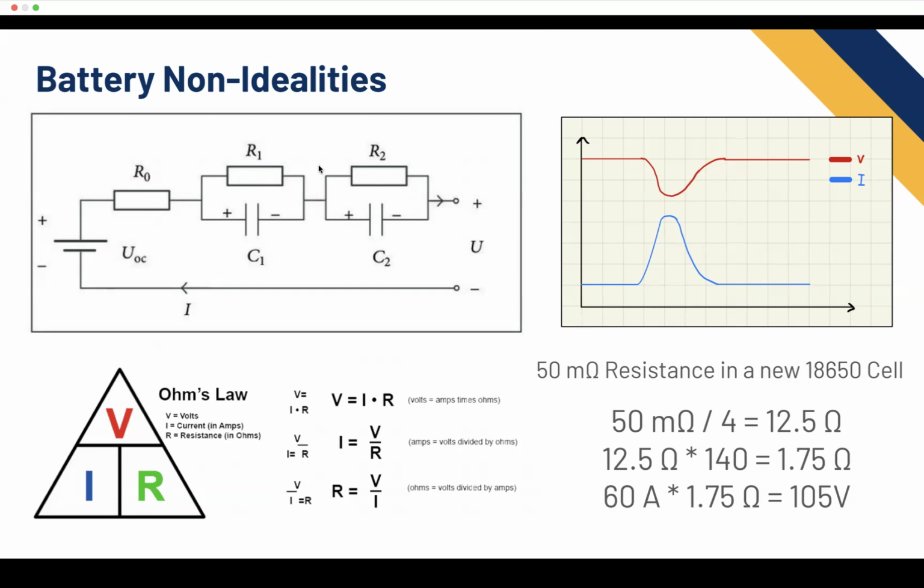That would be 4RC, which is counterintuitive because it's actually 5 resistors and 4 capacitors, but it's called 4RC. Or you could count it as 1 more of this added on right here before you got to your output.